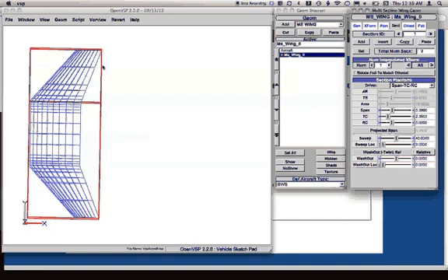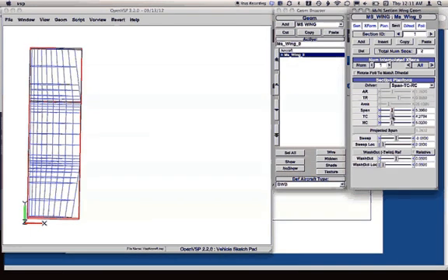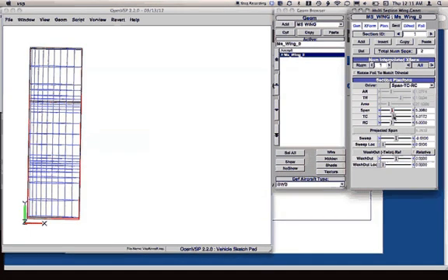So in this case, we have the outboard section. Again, we're going to come in here and say, we want to make this rectangular. We'll take the sweep away. So there's no sweep. And you notice since we now have a varied tip chord and root chord, there is going to be a trailing edge sweep in this case. And again, you can change where that sweep is located. In this case, we're just going to leave it and not worry about that. Make it rectangular. We're going to take our tip chord, make that a little bit larger here, and now we have a rectangular wing. Very simple wing geometry.